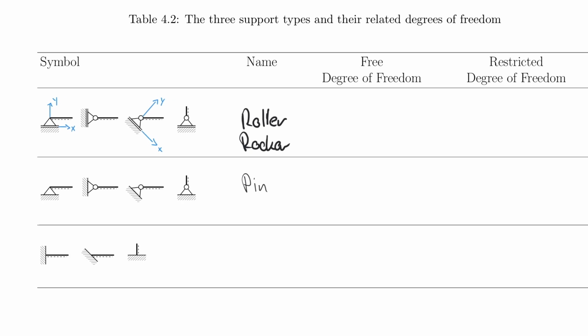So we have degrees of freedom, and the degree of freedom in this case is really in the x direction, right? And that is probably the more obvious one to see because the picture nicely shows the plane. But keep in mind the circle here and the fact that this part of the beam is actually free to rotate about this point. So therefore I have a second degree of freedom for this one, which would be rotation about, and important, about the z-axis.